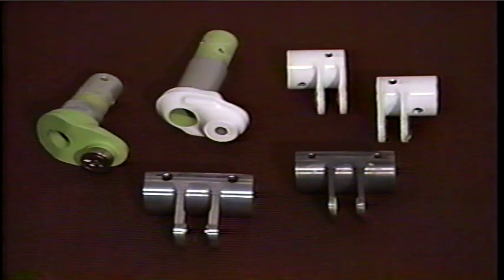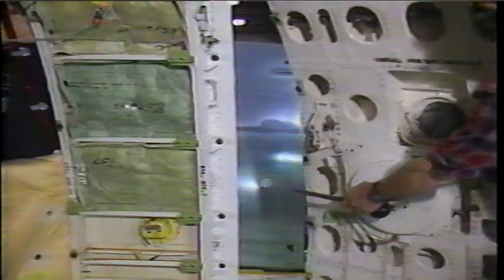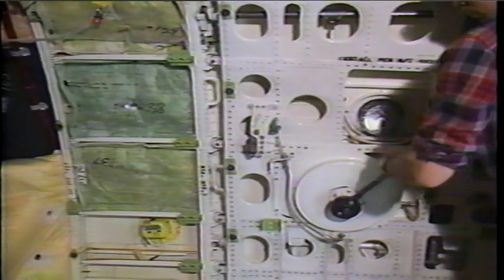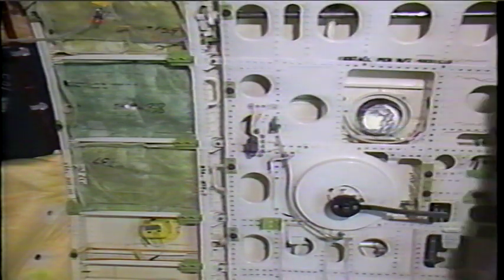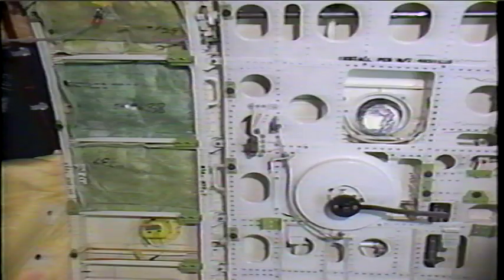Note the components of the latch torque tube subassemblies are similar but are not necessarily interchangeable. Be careful not to mix up similar components between doors. Start with the door closed and the latch and gate push rods connected to the latch torque tube. Position the interior handle in the door latched position. Adjust the lower gate first, then the upper gate.